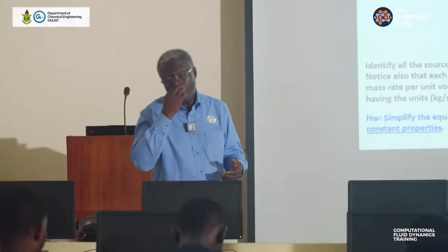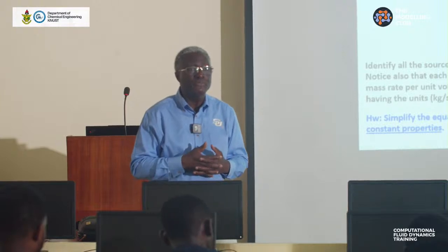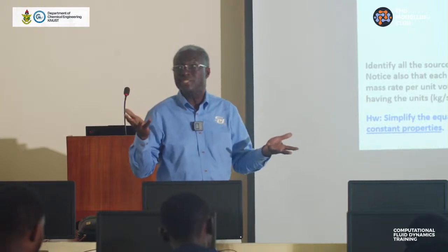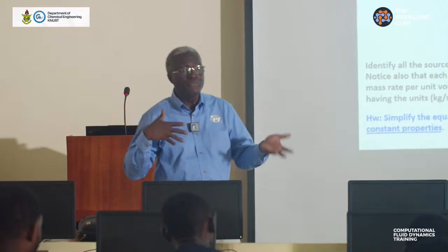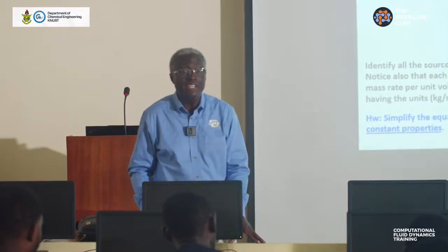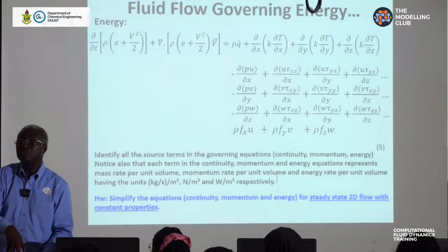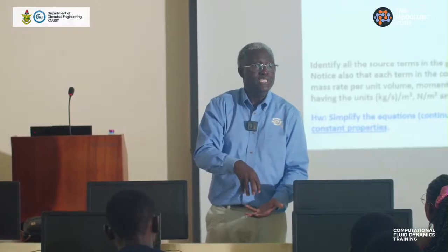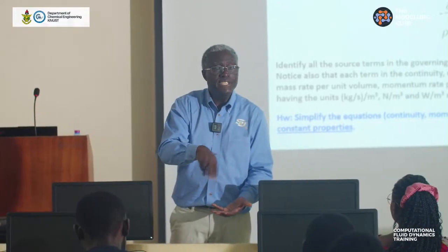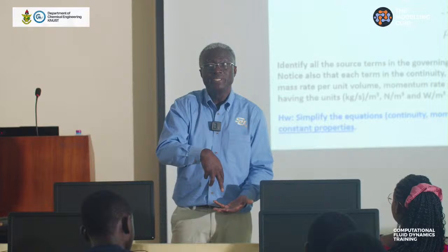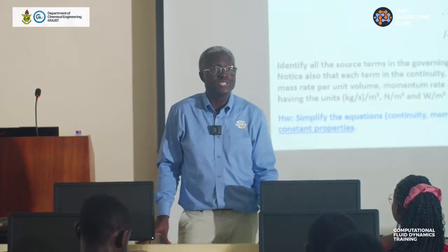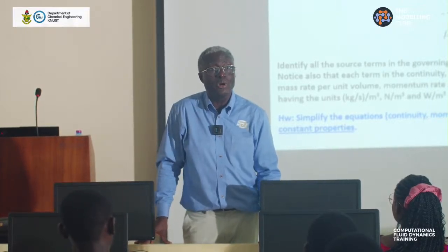Examples of source terms would be in a nuclear reaction, whether you have fission or fusion, you have internal energy generation taking place that has to be accounted for. Or let's say that you are doing a process reaction and you insert a heating system into your process tank, resulting in internal heating of the fluid. That is also a heat source in your process that you have to account for.